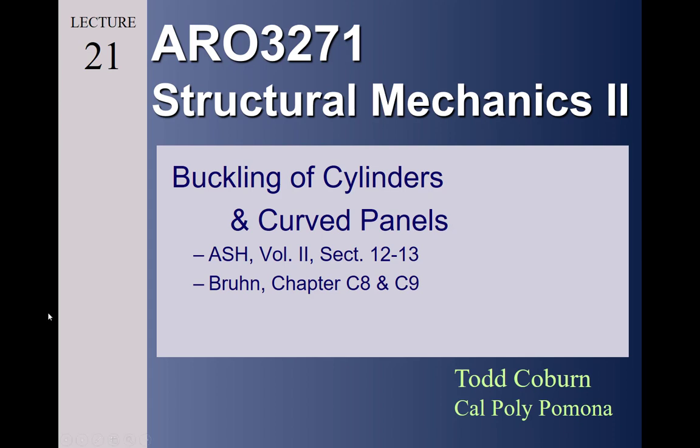The good news is what we're going to cover today is going to be a baby step forward from what we've already learned, because the methods we're going to use to evaluate the stability of cylinders and curved panels is really the same as what we learned for flat panels. The only difference is that now we will be going to a different curve for buckling coefficients, and also we will be using, in some cases, slightly different variants of the equations.